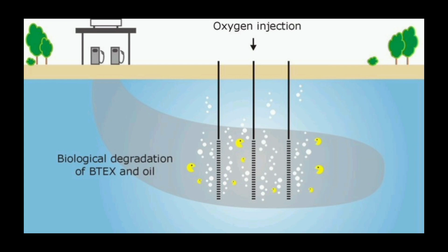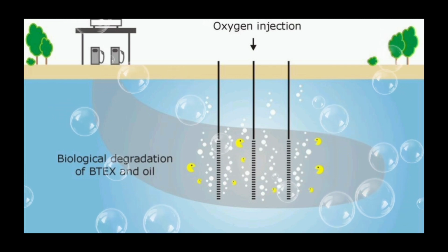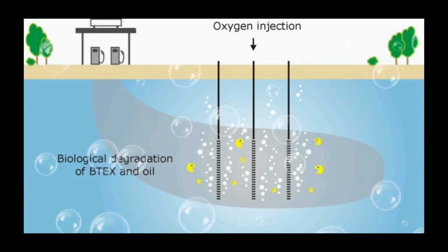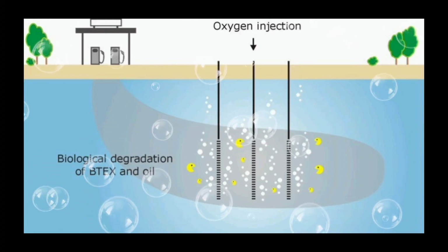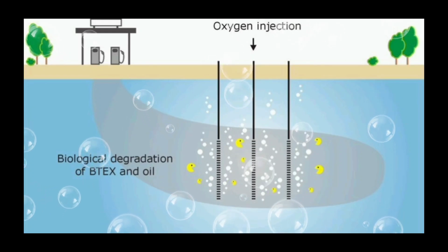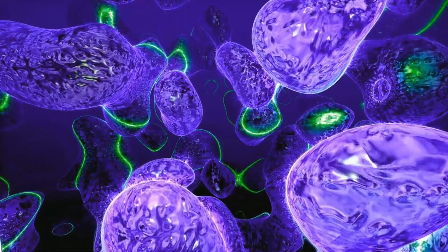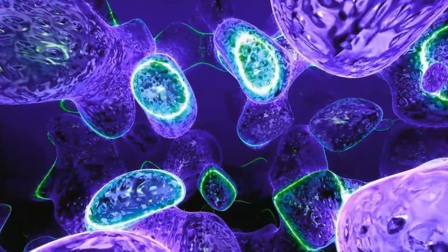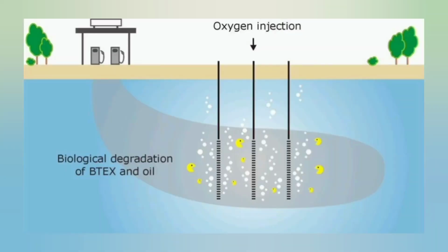By giving oxygen to the microorganisms and increasing the interactions between air, water, and the aquifer, the injection of air and gaseous nutrients if needed promotes the development of the aerobic microbial population and thereby enhances the bioavailability of pollutants. The goal of a sparging system is to increase pollutant biodegradation while minimizing volatile and semi-volatile organic compound volatilization.